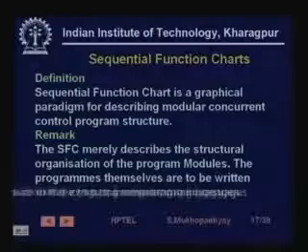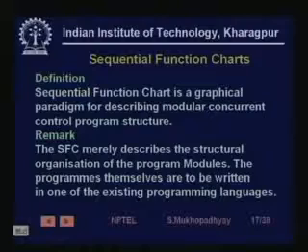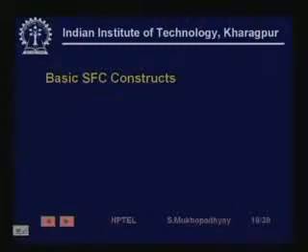So you have this remark which says that the SFC merely describes the structural organization of the program modules, while the actual program statements in the modules still have to be written, probably using existing PLC programming languages, something like either RLL or instruction list or whatever. So let's take a quick look at the basic SFC constructs. They are basically state machine like constructs and contain some simple programming constructs with which we are familiar.